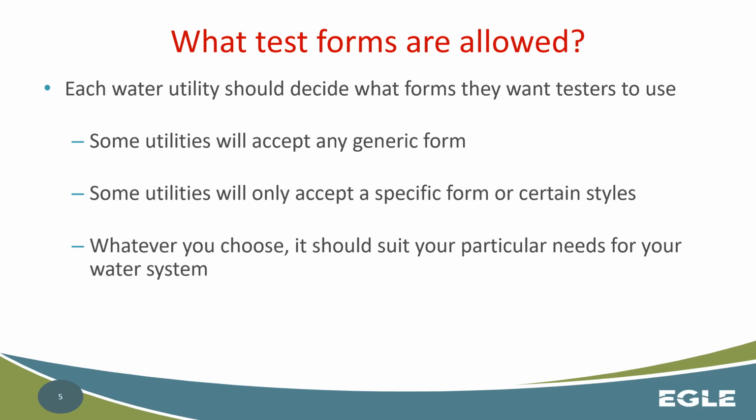Another thing you should be looking at is, after these things have been tested, there's supposed to be a tested date tag attached to the assembly. You should maybe spot check to make sure that the form matches the tag. Make sure the tag is even there on the assembly itself, because that tag gives someone the trail, quote unquote, of the paperwork. I could look at the tag, see the code, go to the city, and you should have that paperwork. That's where you need to maintain that stuff. All right.